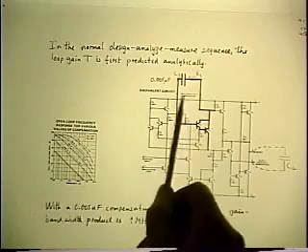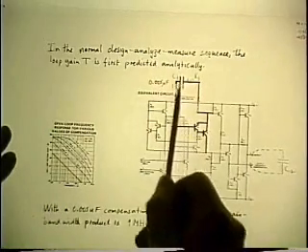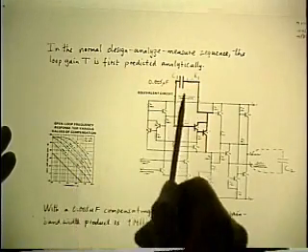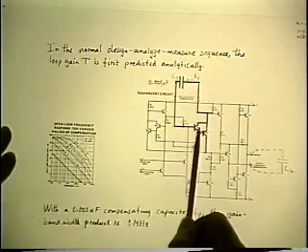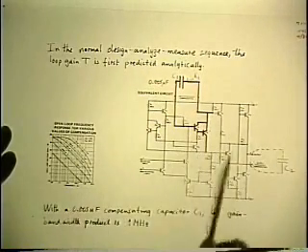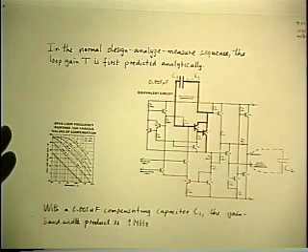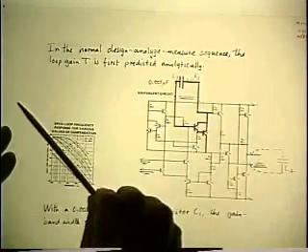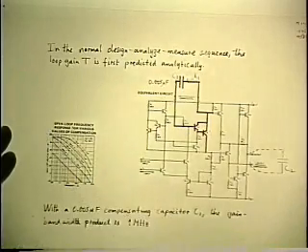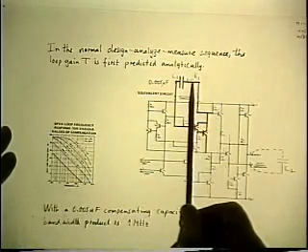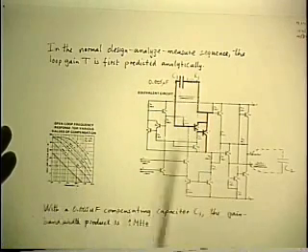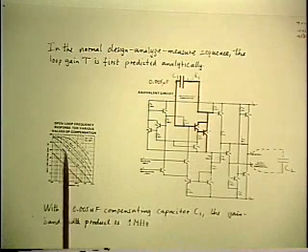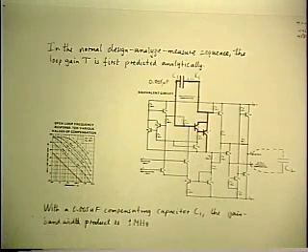So the IC chip designer said, when you put a capacitor of 5,000 there, you'd better put a resistor of 1.5 K as well in order to give a 0 in the response, in order to cancel the 22 kilohertz pole that is somewhere else. And that's why it doesn't show up, because it was purposely designed to cancel it out. But when I neglect to put that resistor in there, that 22 kilohertz pole, which is somewhere else, is no longer compensated, and it showed up in the result. And that's what made it go unstable.